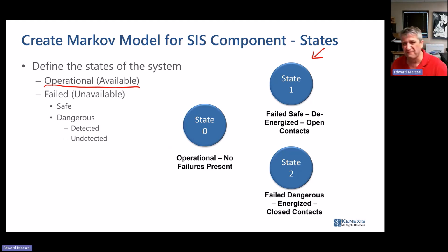Well, failed safe and failed dangerous are actually more akin to effects than failure modes. And they allow you to collect a bunch of failure modes together that will put the system in a certain state. So if you think about failed safe, that's where we're de-energized or our contacts are open.